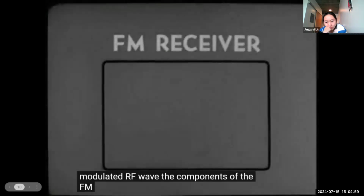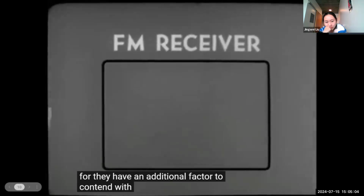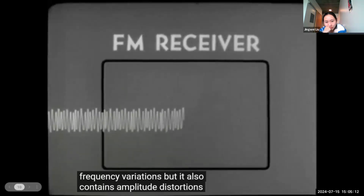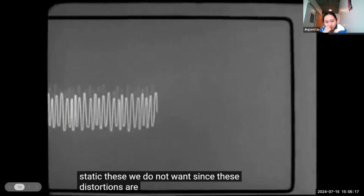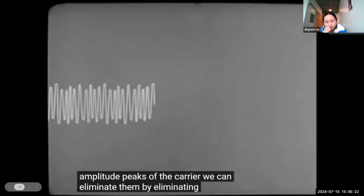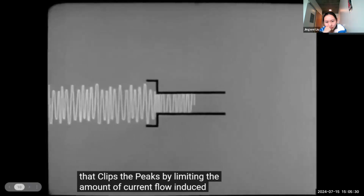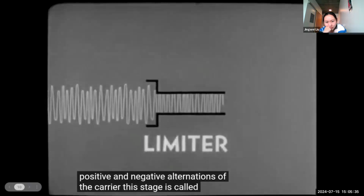The components of the FM receiver are a bit more complex, for they have an additional factor to contend with. The incoming carrier contains intelligence in the form of frequency variations, but it also contains amplitude distortions, hash and static. These we do not want. Since these distortions are located along the amplitude peaks of the carrier, we can eliminate them by eliminating the peaks. This is accomplished by a circuit that clips the peaks by limiting the amount of current flow induced by the positive and negative alternations of the carrier. This stage is called a limiter.